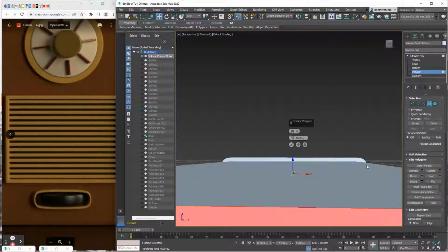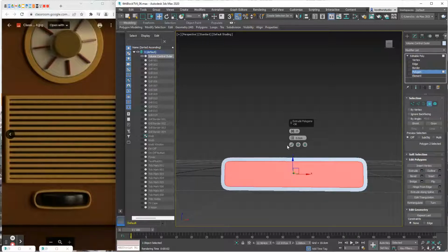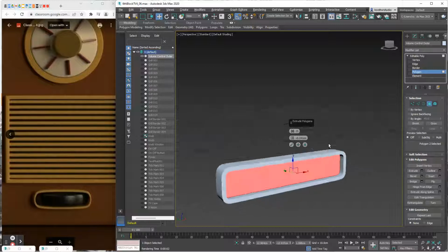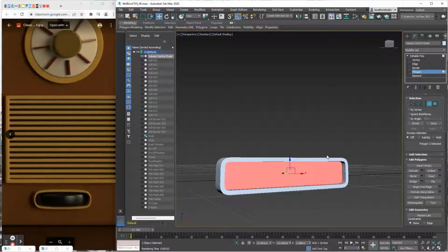And then I'm going to click the Extrude tool, and 10 is definitely not what I want to do on the extrusion. I want to extrude in, so that's going to be a negative value. Went too far. That ought to be good right there. All right. And let's see. I'm pretty happy with it. I think it should be okay.